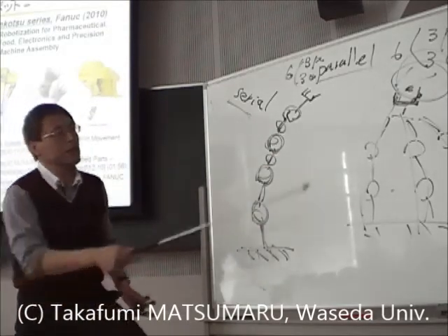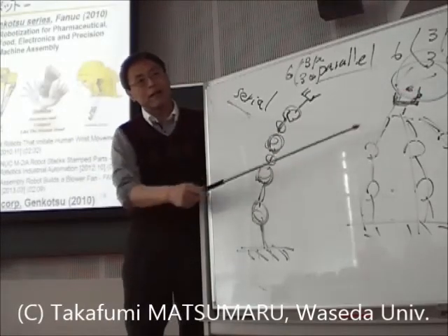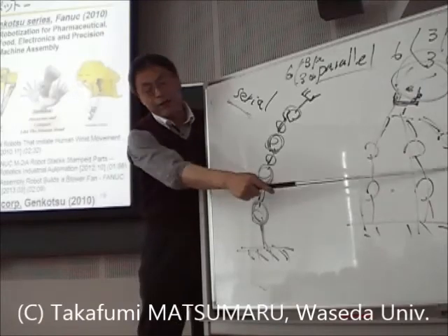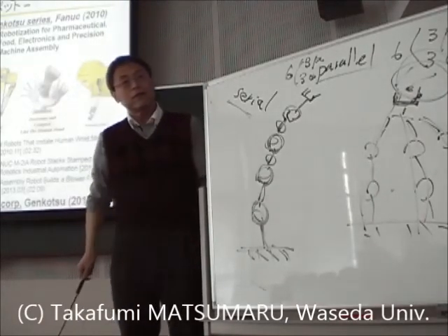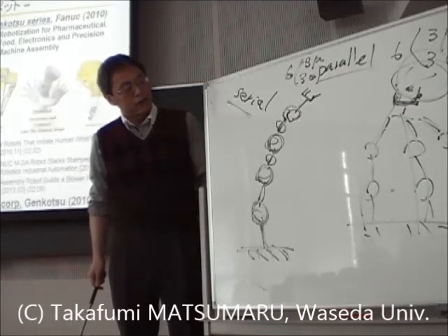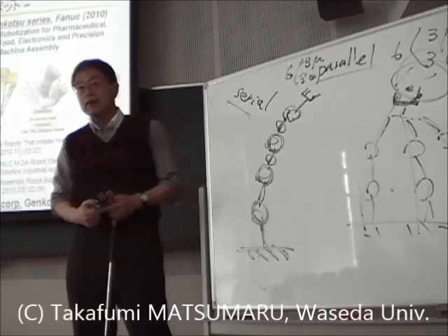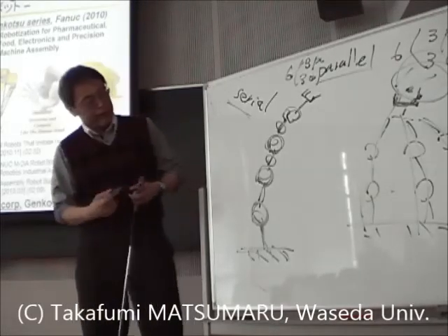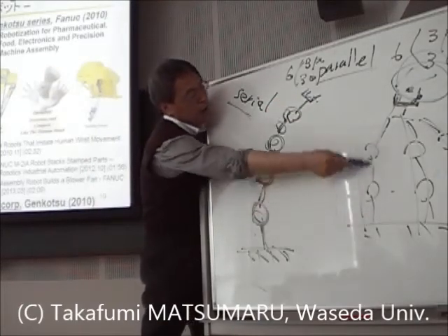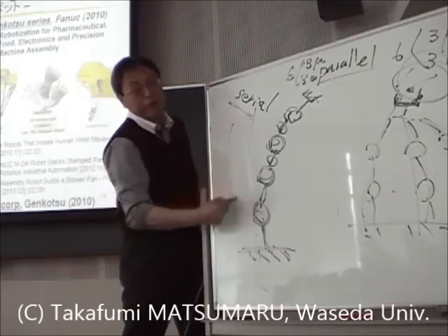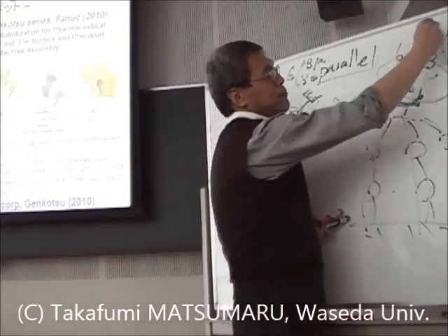What is the special feature? Yes, a larger payload can be carried when supported serially, and what? I think if one joint is broken in the serial, maybe the whole arm or the whole robot is affected. One important thing is working area, because the serially connected one has a wide range of movable area, but the parallelly connected one can work only in a limited space.